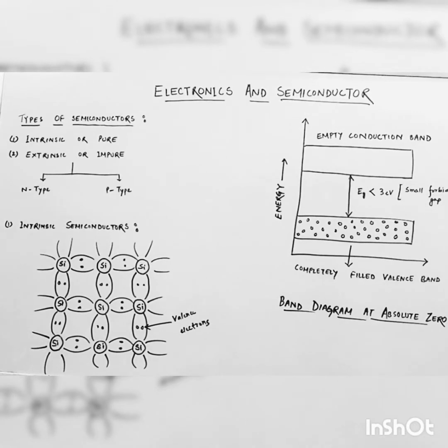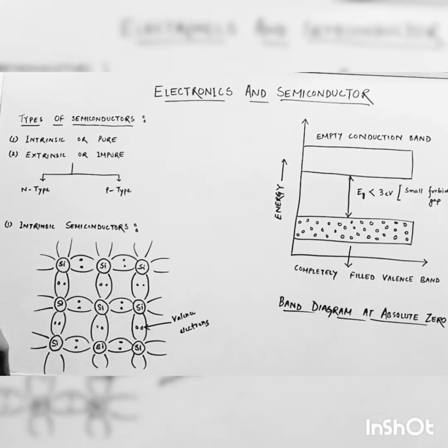So these semiconductors, what happens, you can see here an example. I have taken the example of silicon, germanium. Natural pure germanium is also an example of intrinsic semiconductors. So at suppose 0 degree Kelvin, what happens here? The valence band is completely filled, and the electrons are forming bonds between the atoms of the silicon. Okay, so therefore at 0 degree Kelvin, this pure semiconductor is behaving like an insulator. There is no conduction yet, because they are at 0 degree Kelvin.